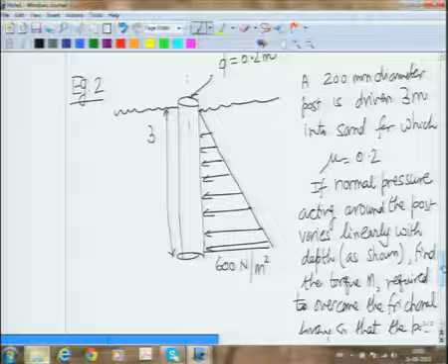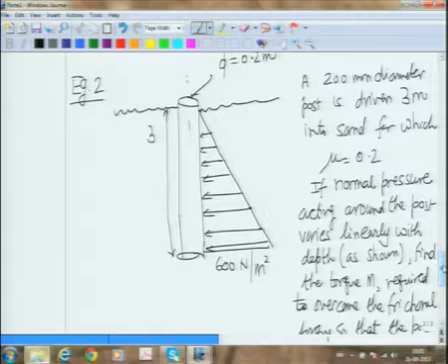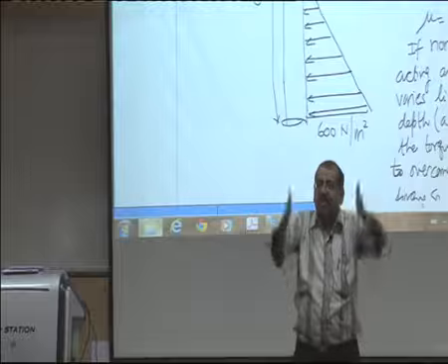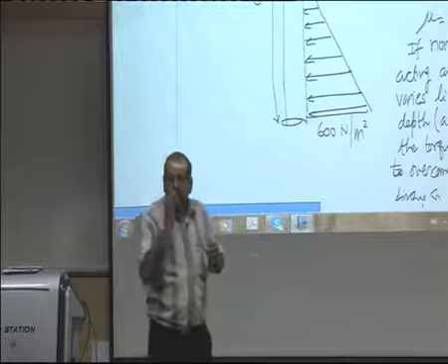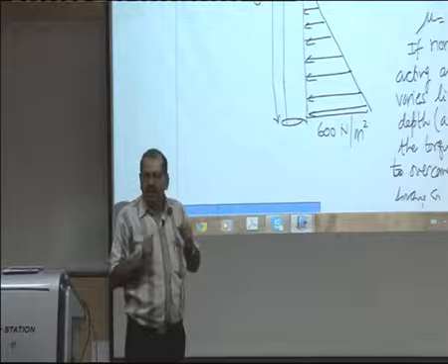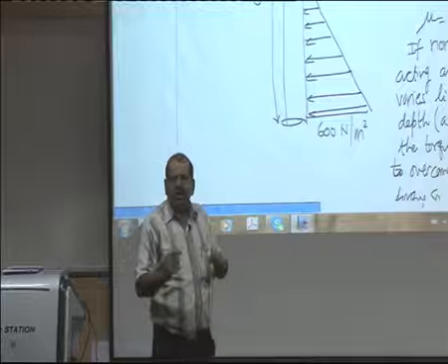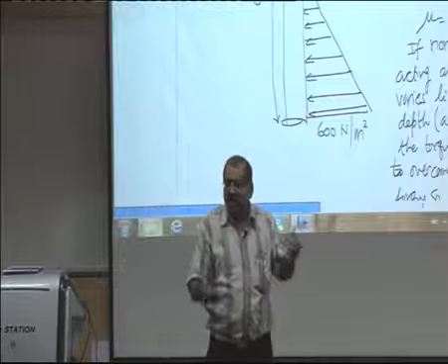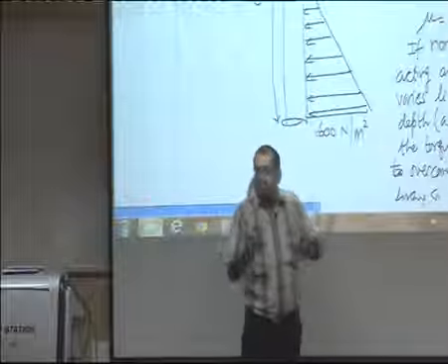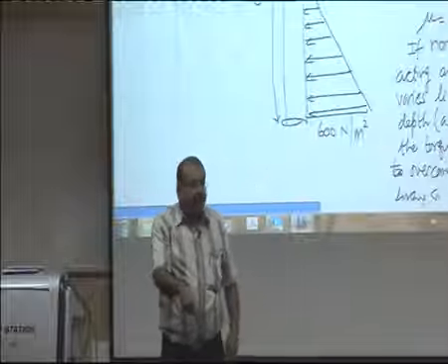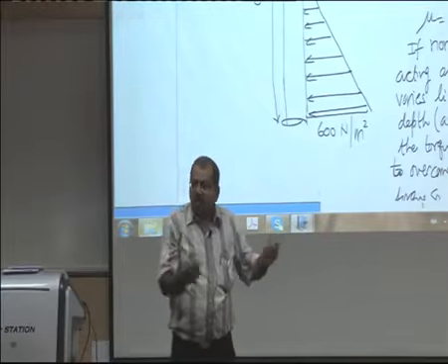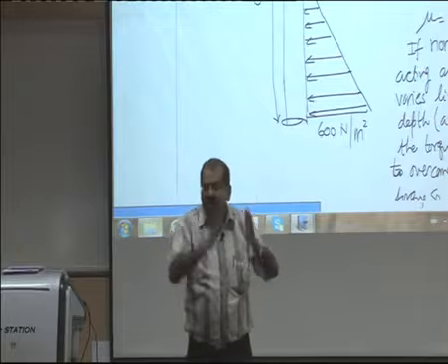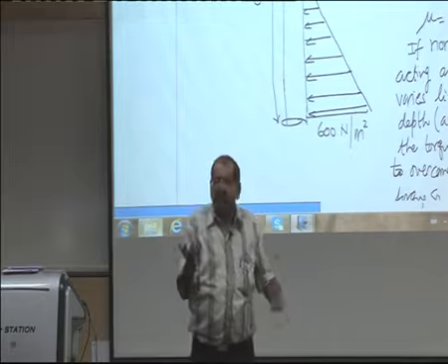So now what you have to do is choose an element of area not on the flat surface but on the lateral surface, because you have to identify the contact area. The contact area is the curved part of the cylinder. So on that you have to choose a small element of area. Now what you may also realize is that this problem is axisymmetric. That means the pressure which is given is varying with depth, but all along the circular cylinder it is the same. Nothing is given, so we'll assume it's the same. Axisymmetric means things don't change with theta.